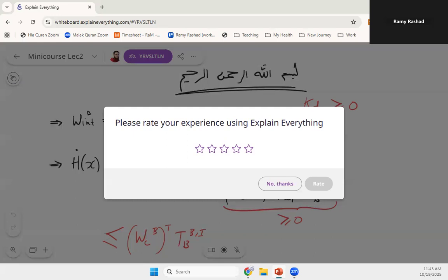The only problem is if you change the stiffness, you're changing the potential energy. If you change the desired inertia, you're changing the kinetic energy. And then you have non-passivity. Yes, you lose the passivity in both cases. That's correct. So just to confirm finally, passivity implies stability. Yes, if you have a passive environment. Or we could have a setup where the controller itself is not passive, but the whole setup combined with the environment appears to be somewhat stable.